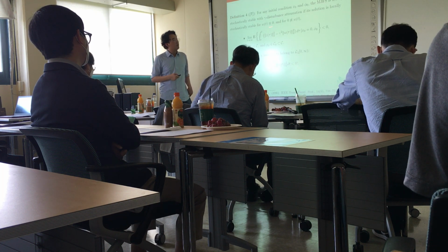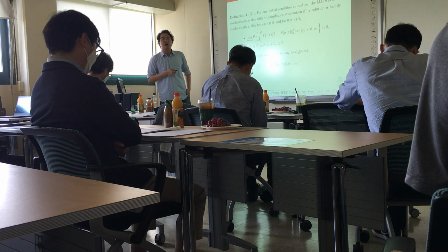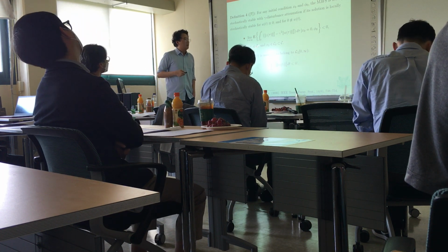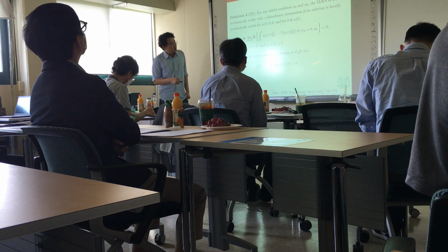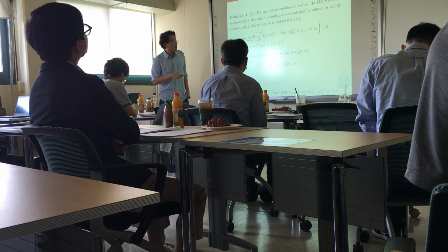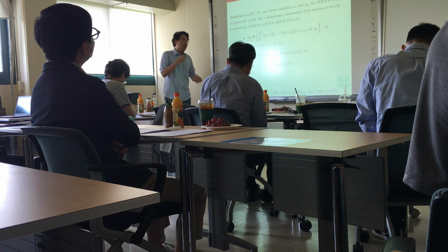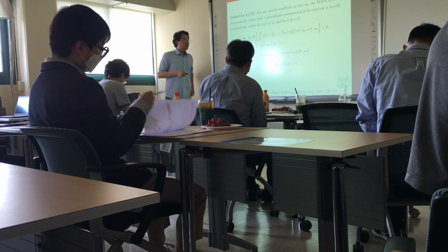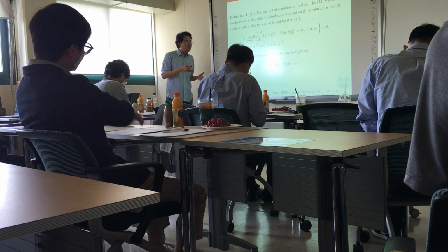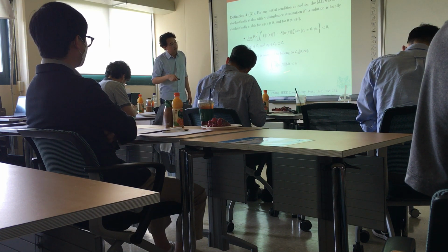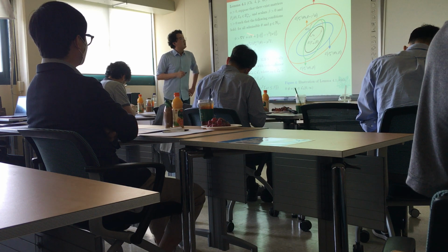So here we also give an example. We modify the definition of H-infinity performance so that we also add the local condition. So now we have to make the assumption that the control input and the disturbance have bounded energy that is satisfied with the following inequality.